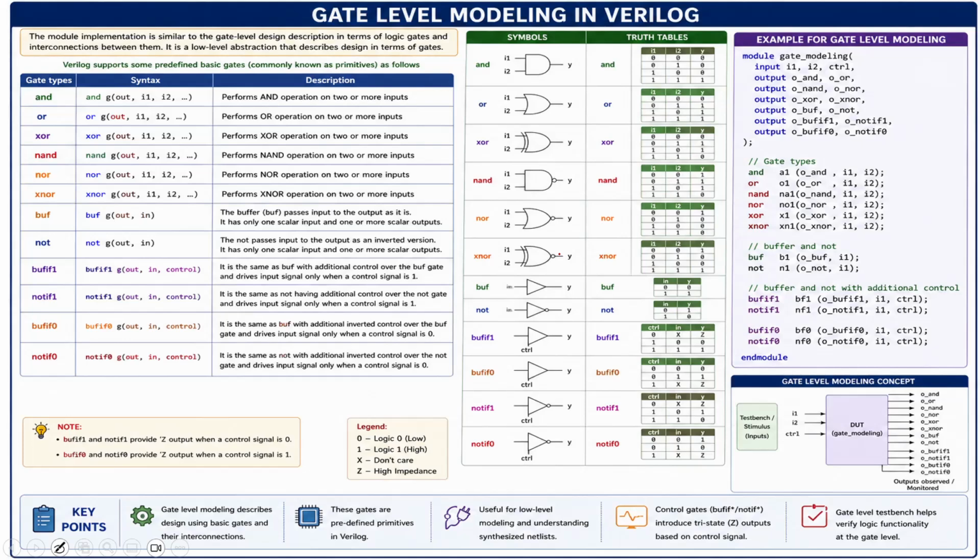In terms of design, using gates should be the lowest priority. Sometimes we use them, because in our modules the built-in operations are there. These are user defined primitives, UDPs: AND gate, OR gate, XOR gate, NAND gate, NOR gate. These are the buffers. There is a control signal, and based on the control signal the output is low, and sometimes high.